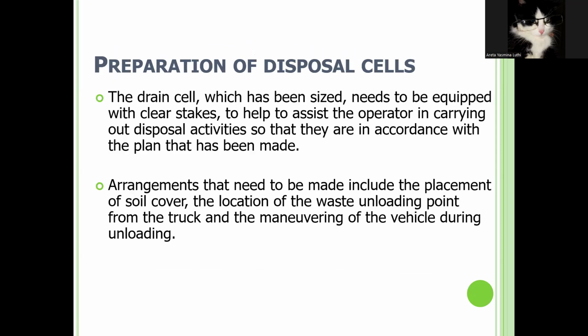And preparation of disposal cells, the drain cells which have been sized need to be equipped with clear stakes to assist the operator in carrying out the disposal activities so that they are in accordance with the plan that has been made. And arrangements that need to be made include the placement of soil cover, the location of the waste unloading point from the truck, and the maneuvering of the vehicle during unloading.